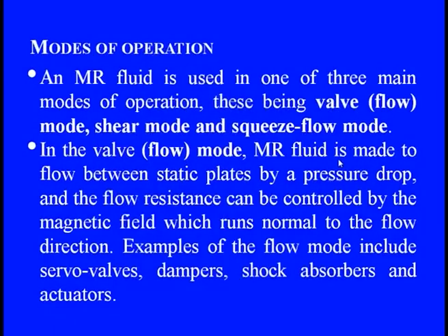Now we are discussing the modes of operation. What are the basic modes? An MR fluid is used in one of three modes of operation, where the direction features are important. The first mode is the flow mode, sometimes called the valve mode. The second mode, as we discussed previously, is the shear mode. And the third mode is the squeeze flow mode.